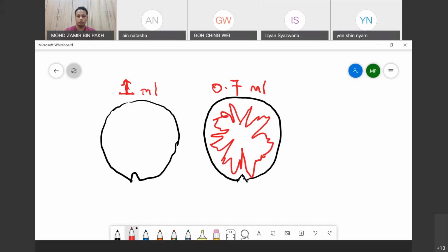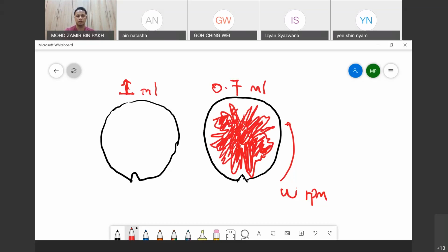Right, so the resist is being dispensed from the center. Then it is redistributed or coated at some speed, omega RPM, for example. Then you will see the resist. Well, if the resist is red in color, then you'll see something like this. The central region and some part at the edge are covered, but some other parts are not covered. Okay, so we'll have something like that, and this is called resist streak.